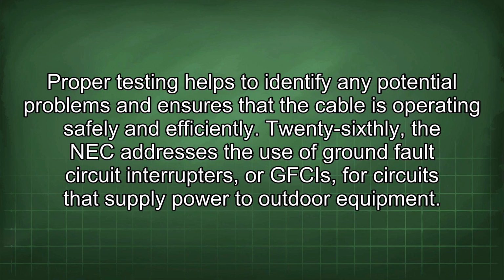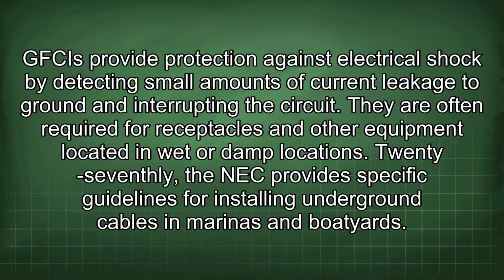26thly, the NEC addresses the use of ground fault circuit interrupters, or GFCIs, for circuits that supply power to outdoor equipment. GFCIs provide protection against electrical shock by detecting small amounts of current leakage to ground and interrupting the circuit. They are often required for receptacles and other equipment located in wet or damp locations.